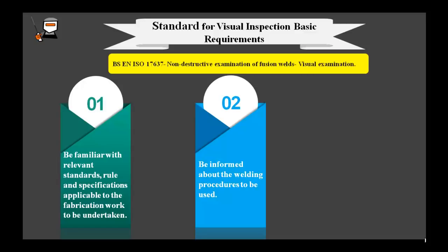For example, you have a qualified WPS for the material A106 grade B or A105 CS flange material or A234 WPB butt weld CS fitting, then this WPS is only for this material. And for example, suddenly you find a welding of A106 grade B pipe with SS flange 316L. You can't weld with the previous WPS for CS, then you have to get a qualified WPS from the QC department for CS to SS material welding.